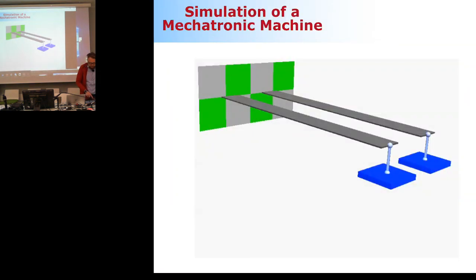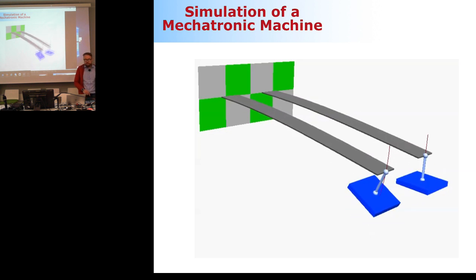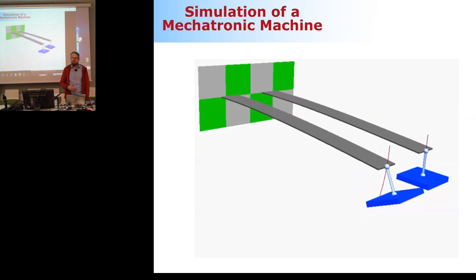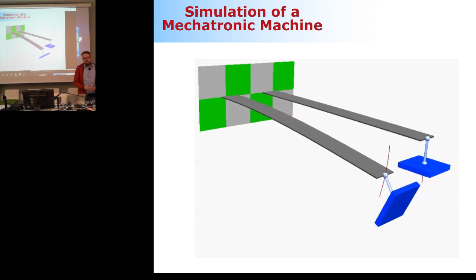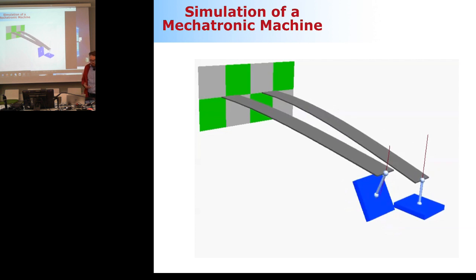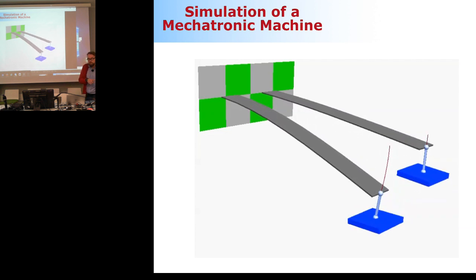Then I have here two cantilever structures. The one where there's a nonlinear strain displacement relationship, another one where there's a linear strain displacement relationship. So which one is linear, which one is nonlinear? I guess this is clear. The one here is nonlinear because it's actually moving also a little bit in axial direction.